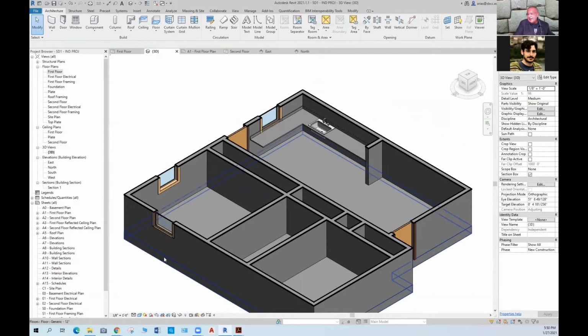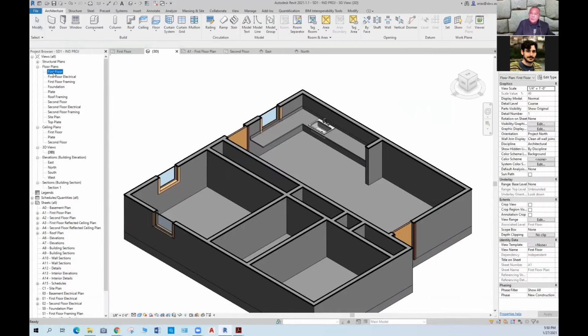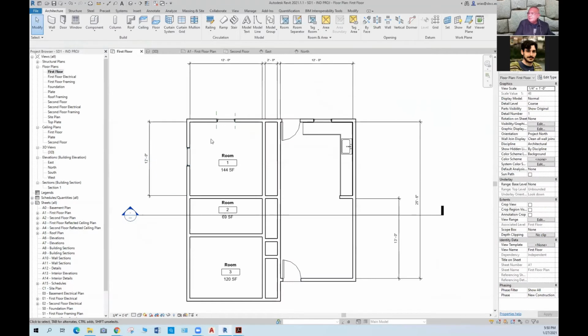And what's the height that we cut the section to in a floor plan? Well, the standard is 4 feet. So if we look at the first floor, this is a section at 4 feet off the ground. That's the height that we are cutting objects. That's why we see this, because this is under the 4 feet height.